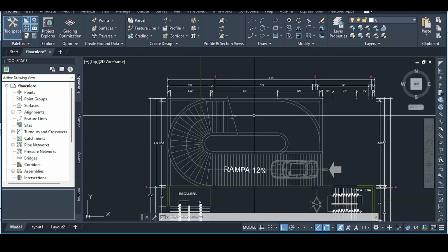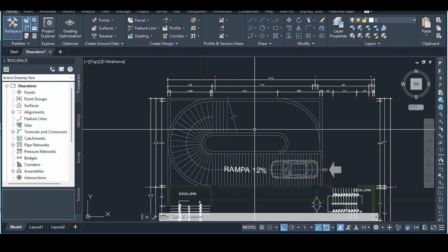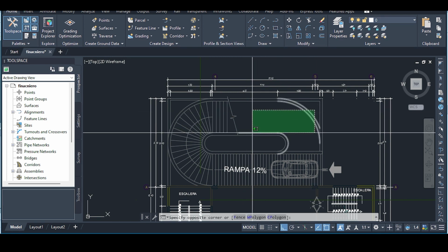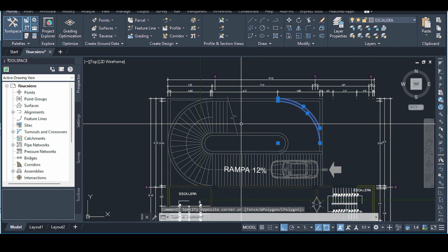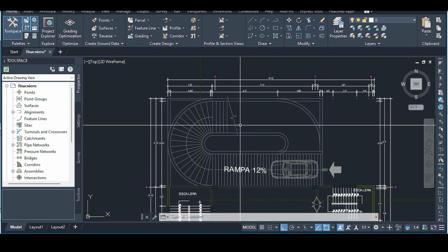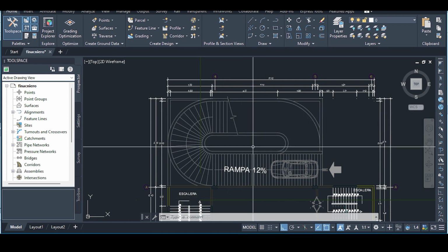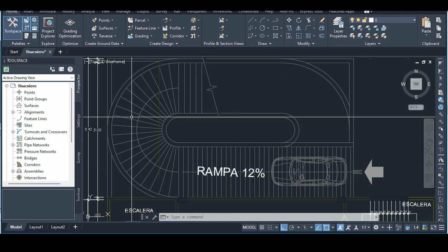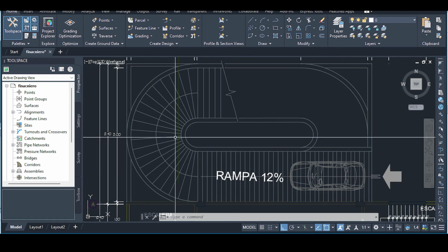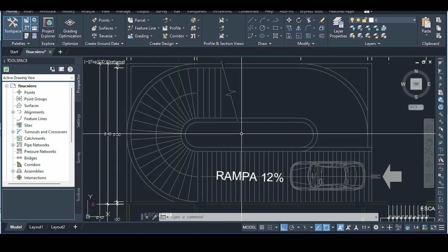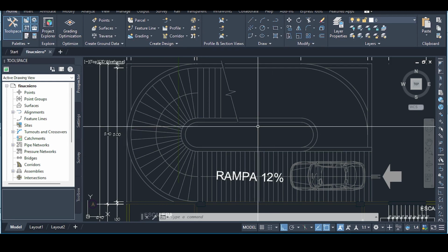Now, usually when an architect suggests a ramp, he sits down with a senior design engineer and tries to lay out the structural system of the ramp. It seems that it's a block here that was used, so I'm kind of disappointed because it doesn't show anything with regard to columns and column setout and how even to do that. The second thing that kind of annoys me is that there is an opening here. Although we said that it's really small, you need to understand that the turning radius, like cars sometimes cannot turn that tight. Why do you have this opening? It's better to have just one wall between them that basically allows for more width, just in case. So I'm kind of not really happy with that.